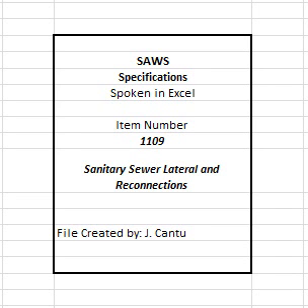Q. No direct payment will be made for hand excavation and backfill when authorized by inspector in locations where excavation by machine is not suitable. R. Payment for service reconnections by open cut shall be considered full compensation for furnishing all materials, labor, tools, fittings, couplings, adapters, stack, disconnecting existing service, up to 10 linear feet of lateral pipe, excavation, trenching, shoring, backfilling, concrete encasement, collars, and all necessities and related work specified herein to complete the task.